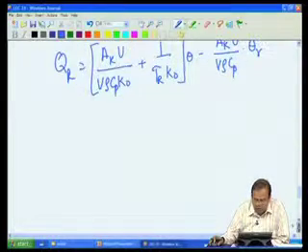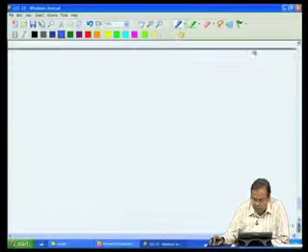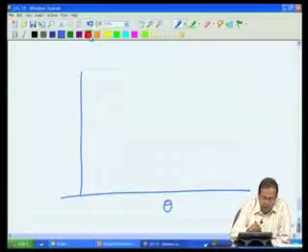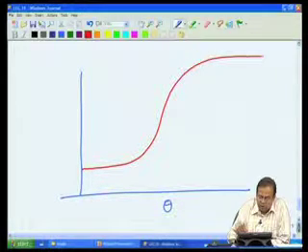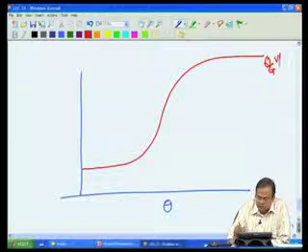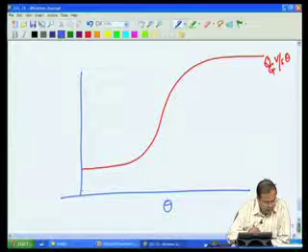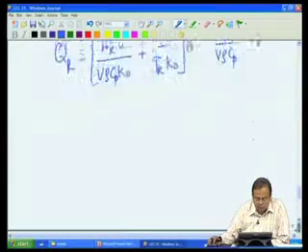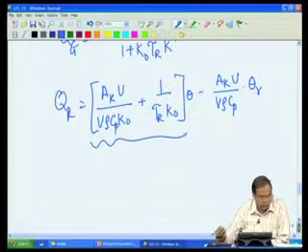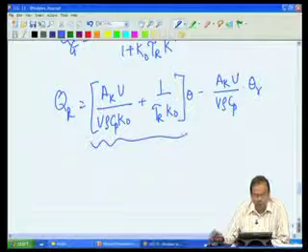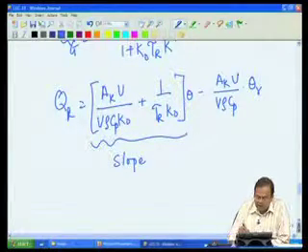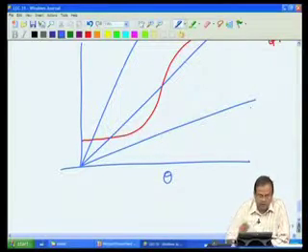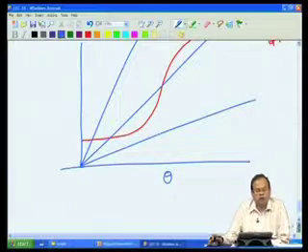So, if we now try to plot this behavior, let us try to once again do the same exercise, temperature and heat generation rate. It actually turns out that we have this very similar shape as before. So, this is Qg versus theta, and we have Qr, which once again can be represented by straight lines with a slope equal to this particular value. So, this is the slope of Qr versus theta, and this is of course the intercept, okay, which can be a non-zero value. But if you just scale it, make a linear transformation, we can show it to be starting from here.